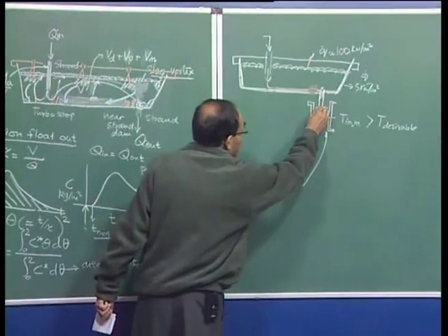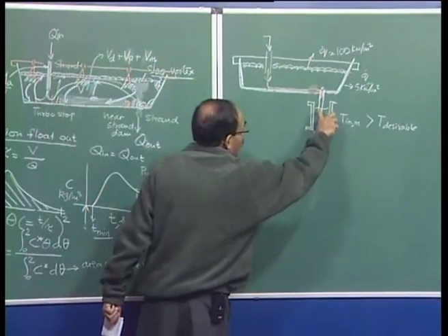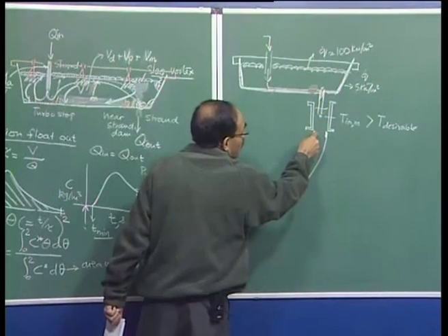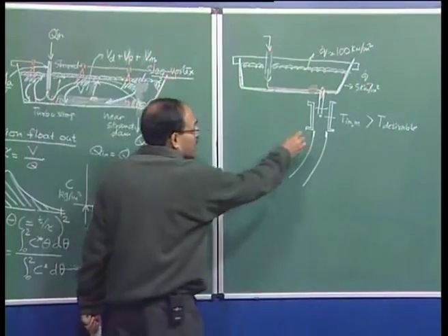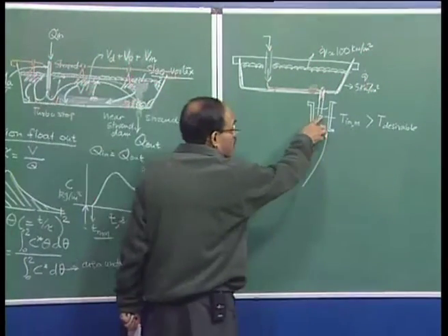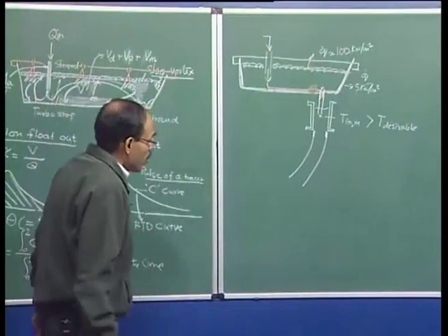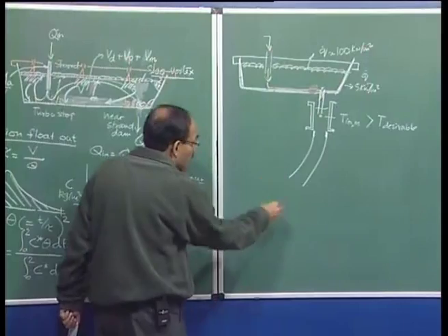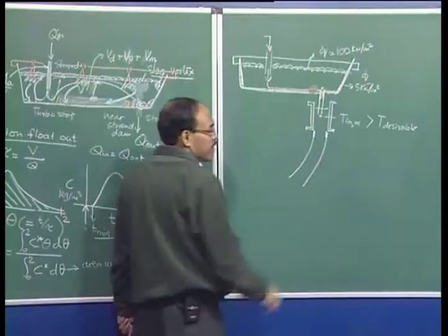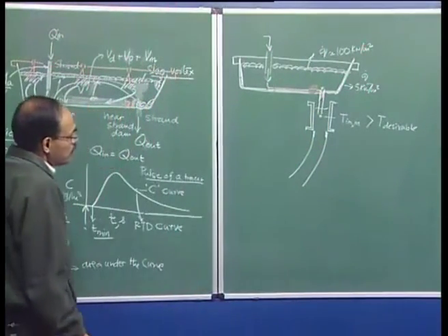Steel has an extremely large density. So, therefore, if we are talking of 1 meter, you can imagine that the ferrostatic pressure here is going to be tremendous, and if the shell is thin, and the thickness of the shell, I repeat again, is a function of the temperature itself. And also the cast composition and the cast microstructure is intricately related to the temperature of